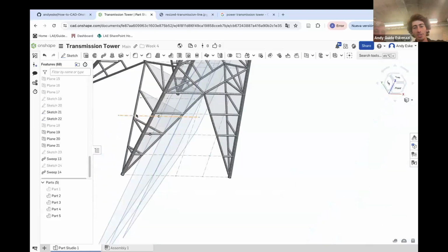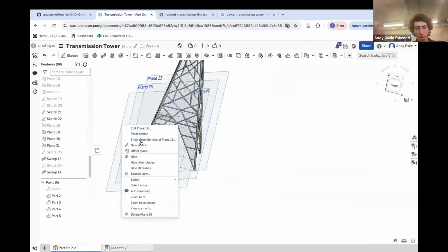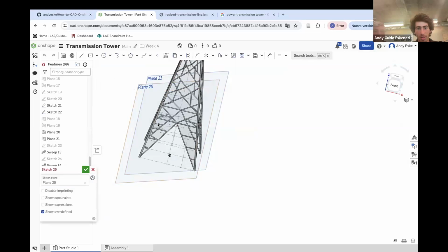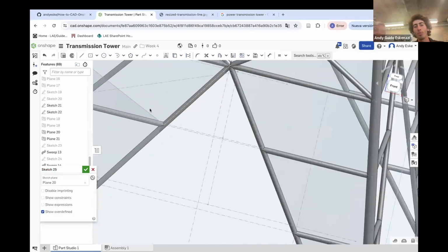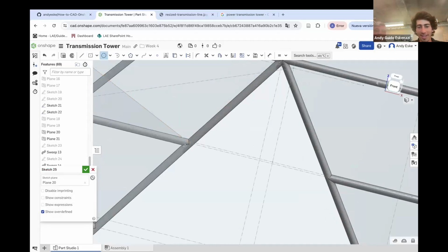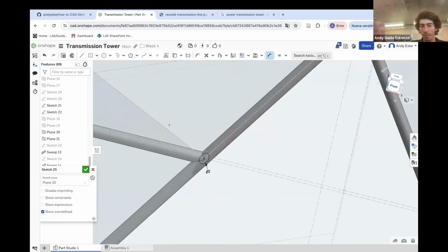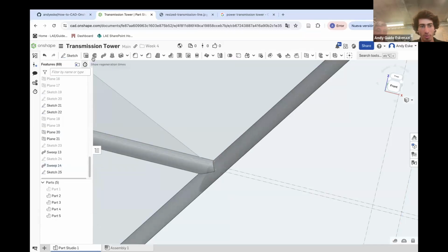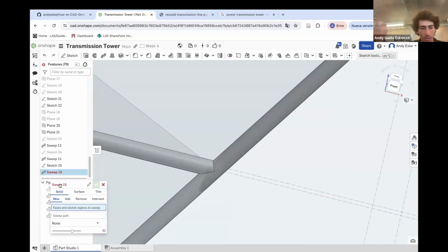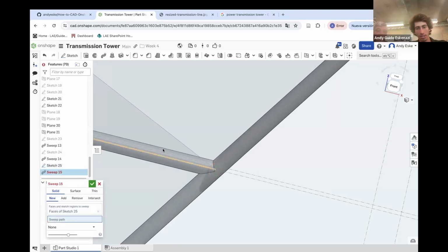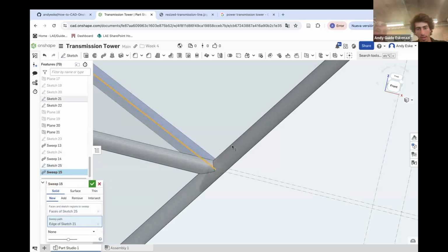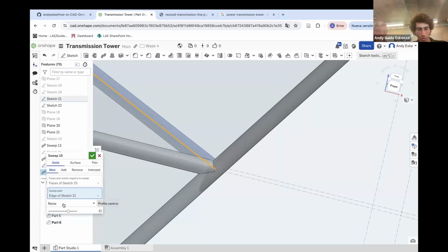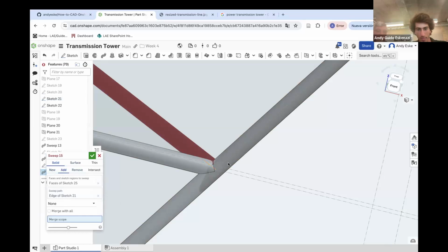Yeah, at least this bottom part of the column is looking somewhat realistic. So then plane 20. After watching this video, you should be equipped to create a lot of planes and use the sweep command, which is this one, super comfortably. Instead of using sweep, you can also extrude as well. That is also a possibility. For now, I'm just using sweep because it gives you control of selecting the path, like we do now, and then asking you here for add.